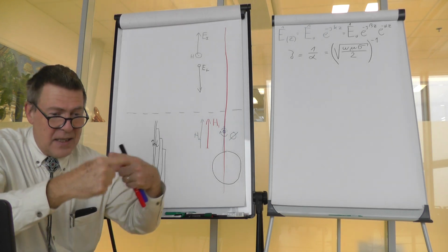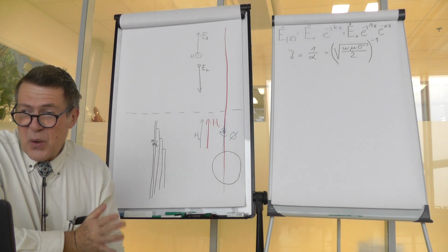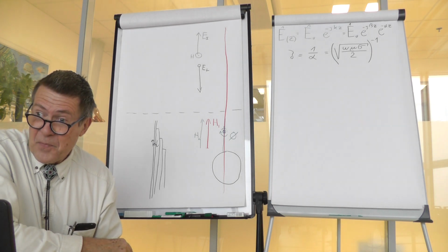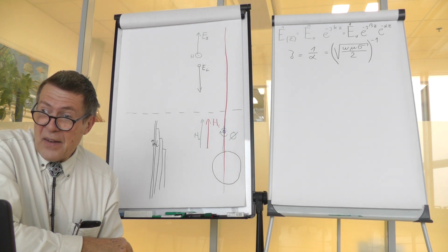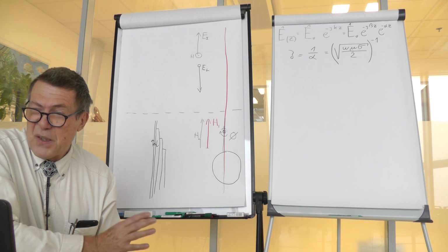For example, there is a number of wires, number of turns in a coil. Then you can go somewhere up to 4 amperes per square millimeter. If you are designing an open air transmission line, you can get to 10 amperes per square millimeter.